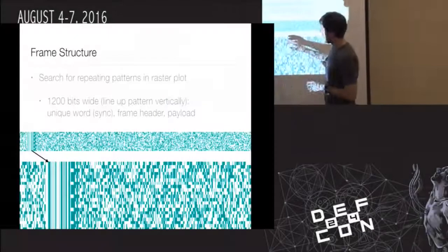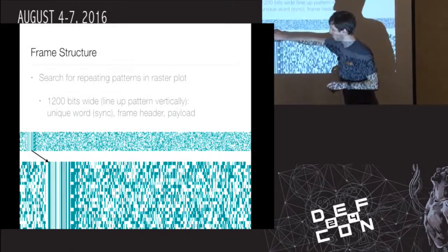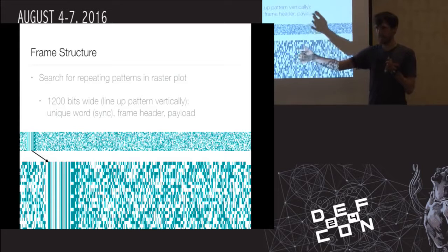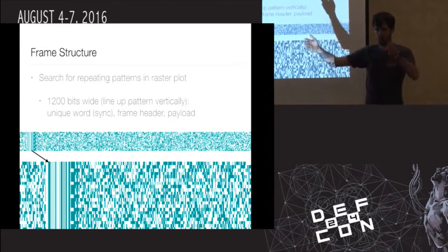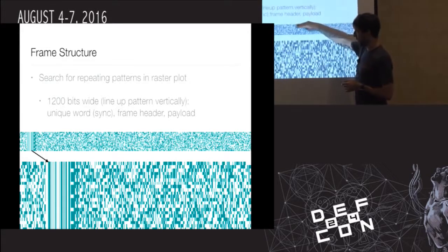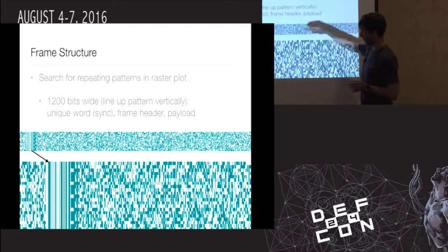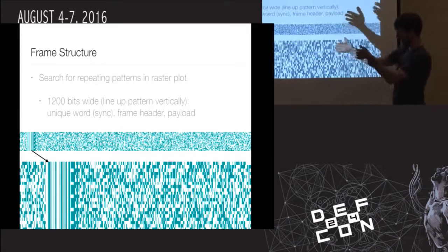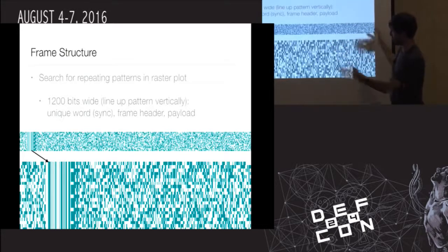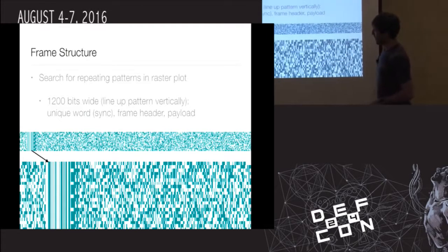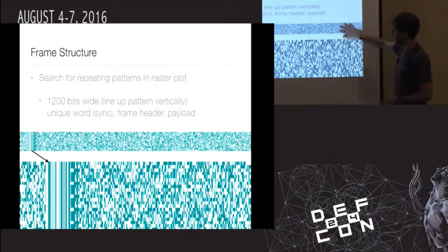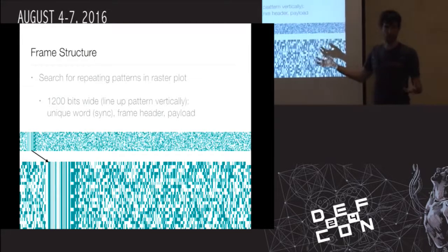Usually when there is some structure like here, you look for the scan line length or your fixed frame length so that they all pile up on top of one another and then you're synchronized, and you'll get these as straight lines. If you're offset, then they're going to be diagonal and you just need to adjust your length until it looks good. Once you do that, you can see here that the vast majority of this packet, or each scan line, looks like it's random, right?